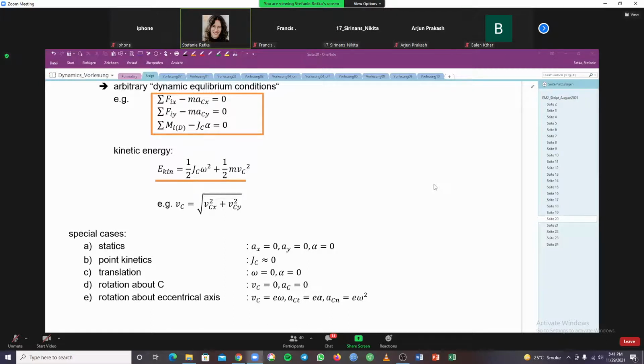velocities acting on the system, then it's probably a kinematics problem. And if you're asked to draw loads, then it's probably a kinetics problem, forces. This is usually stated in the exam. So you need to read carefully. Then usually if you have a system consisting of several masses that are connected by a rope or something like that, then you will need kinematic conditions. But this is also asked for. Usually in these types of problems, part A is to state the kinematic conditions or something like that.